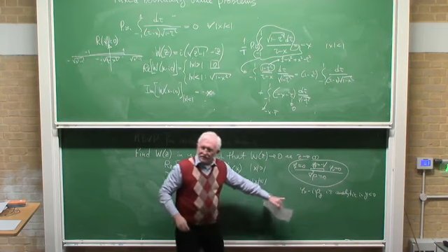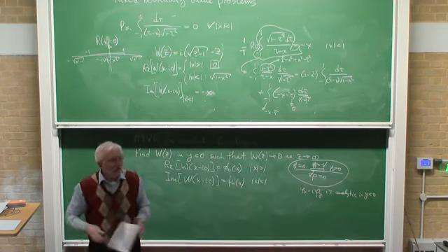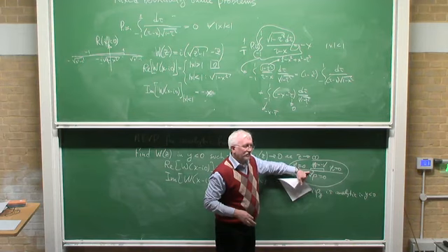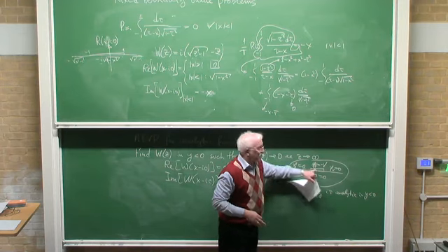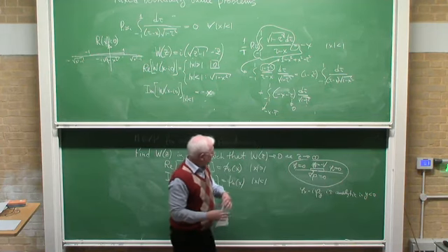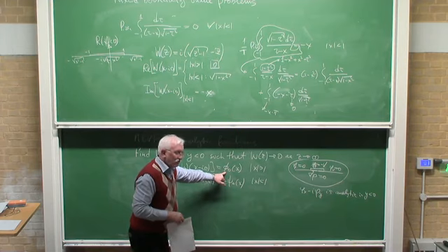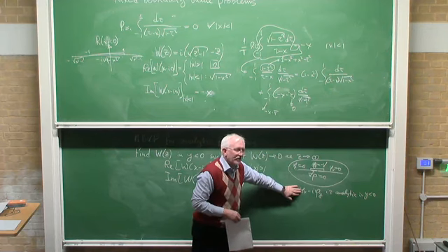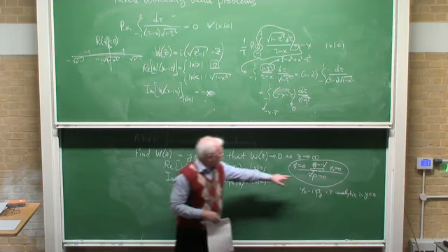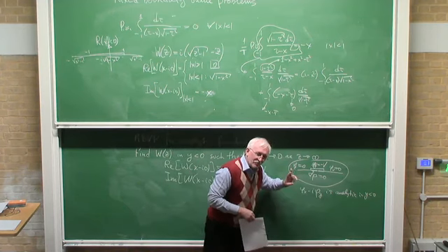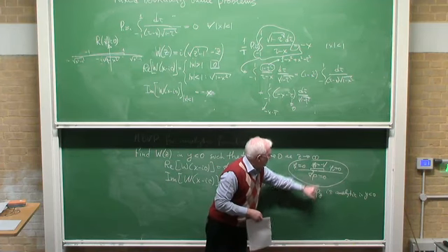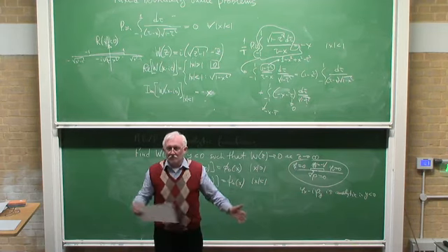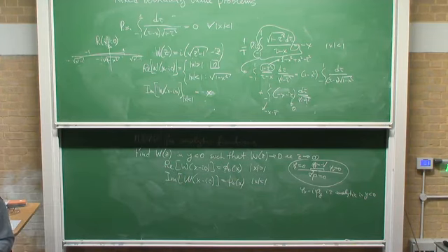So we need to find that analytic function. You can say it's the complex velocity in the lower half plane such that the horizontal velocity is equal to 0 on the free surface, and the normal velocity is given on the plate. And now you are saying, yes, the phi 0 for that problem is 0. The real part is phi x, which is 0. And the imaginary part corresponds to minus phi y. You should not forget about that minus. And that means that psi 0 is v. So always we can do like this.